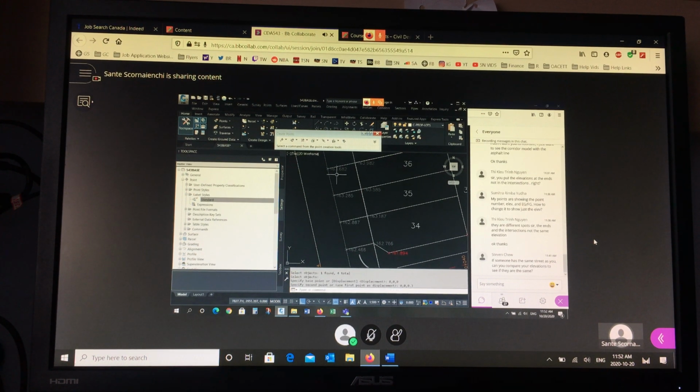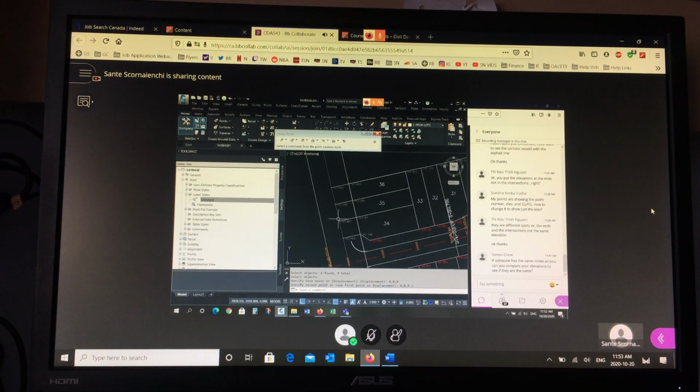So now 0.6 becomes 0.9, 0.2 becomes 0.5, 2.8 becomes 3.1, 2.4 becomes 2.7. I made a copy of this point, I put it here, and I raised it by 0.3. And that's the future proposed point. So that should be on. So these points here should have an EG description. You can keep them in your drawing. And these points here should have an FG description. Their proposed future.